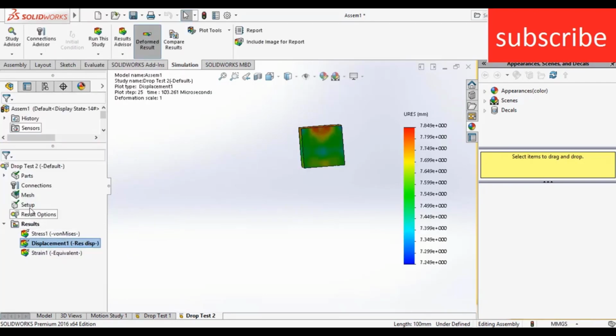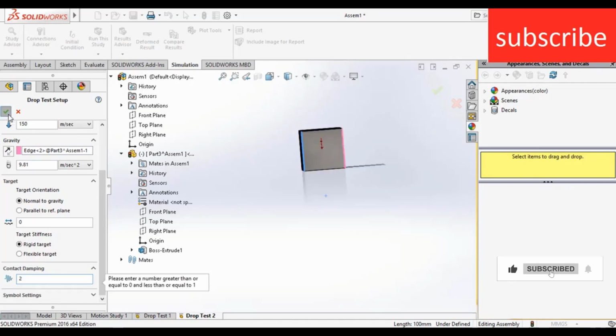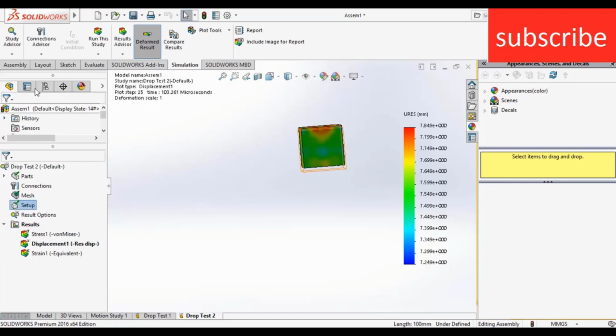Now let's see what will happen when we give a contact damping. For example, let's say 2. Okay, sorry. Basically here it's asking for the value in percentage. When it says 0 to 1, it is asking for the value in percentage. So I have to type 0.2. So click on run the study.